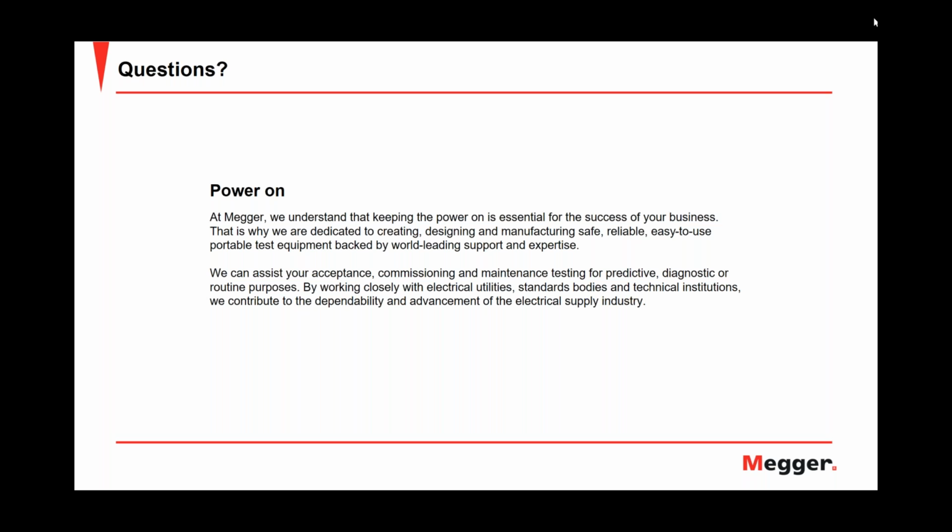And if I look where I connect to my cable and I see I have a bare concentric cable, then my first suspicion is it's probably a bad neutral. And like Javier was saying, if I have a fault, the question is: is it a fault in front of that open or beyond that open neutral? If it's in front, I see it right away with arc reflection. If it's beyond that open neutral point, then I will not be able to see it from that side. And that's when I go to the other side and shoot it backwards. Then I can see the fault, because now the fault is in front of that open.